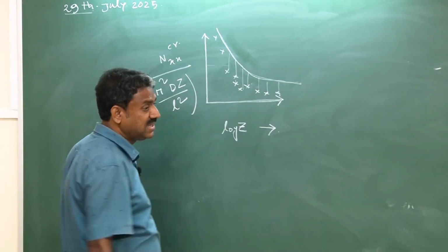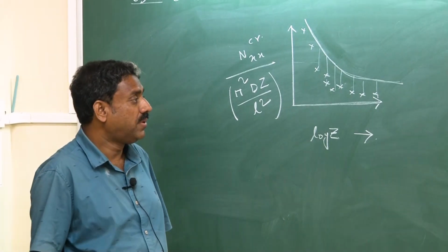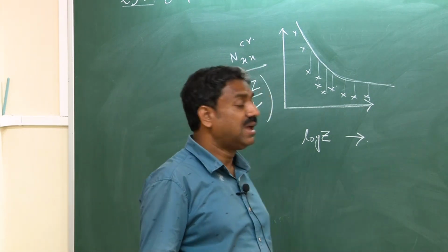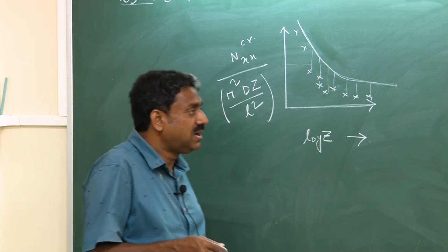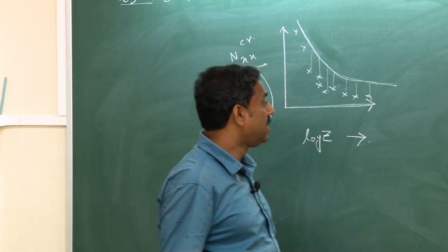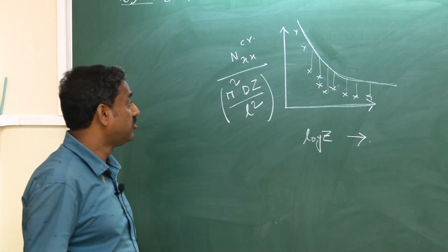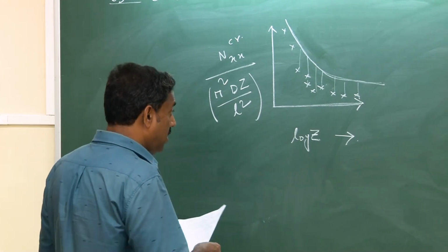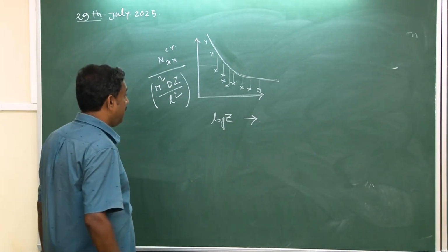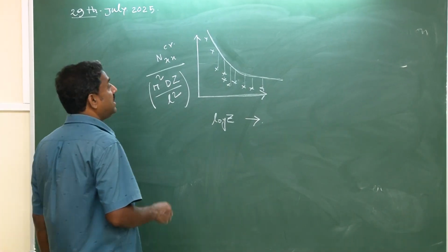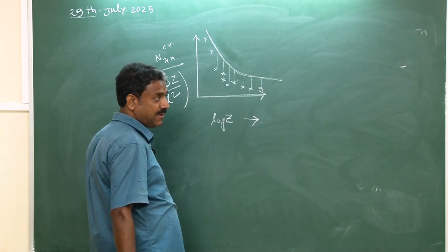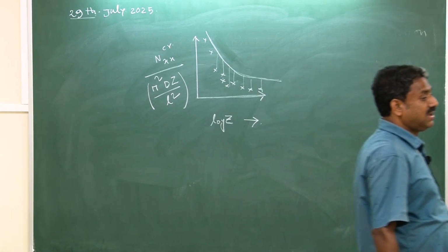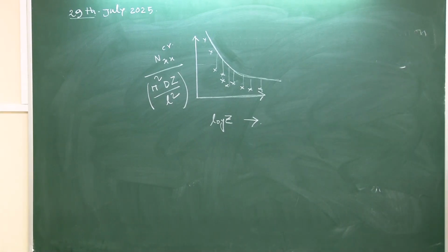Of course, in order to study that load drop, you have to solve it by accounting for the non-linearity, and we are going to use a little different version, but essentially the elements are the same to show this drop. So, this is the most interesting fact here. Now, please note that for the shell under axial force, this kind of drop in critical load is occurring, but you should not be misguided that for all the cases this will be true. No, this is not true.